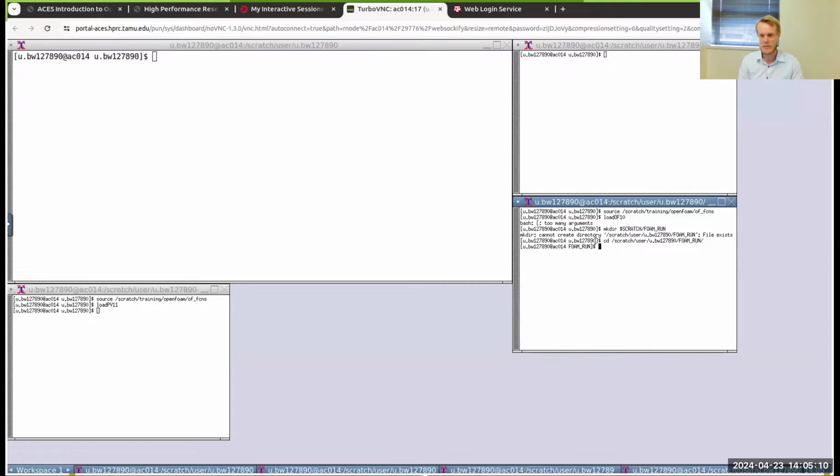Let's go back to this terminal where we loaded OpenFOAM. So now we're going to run a tutorial. I picked the wind around buildings case because it's a fairly simple case, quick to run, but it still uses quite a few of the features that we might be interested in. We have another custom command at our disposal because we loaded that OpenFOAM functions earlier, which is called copy foam tutorial.